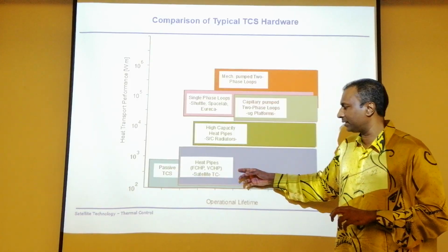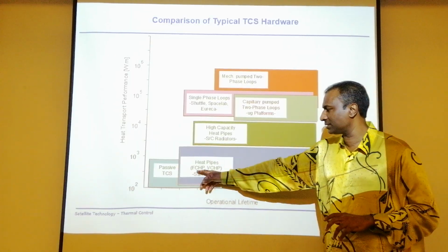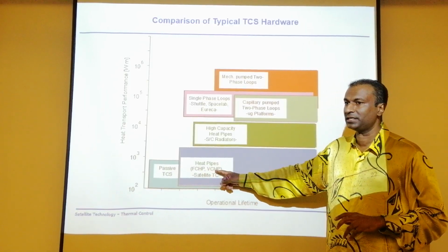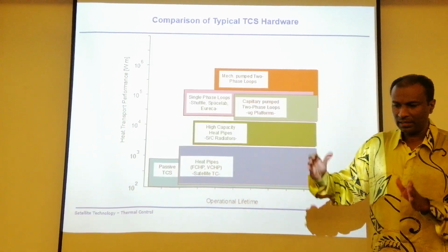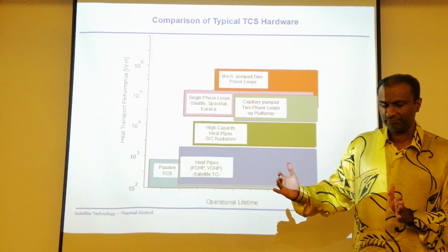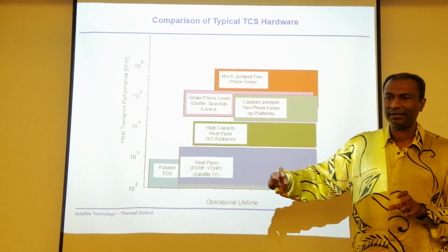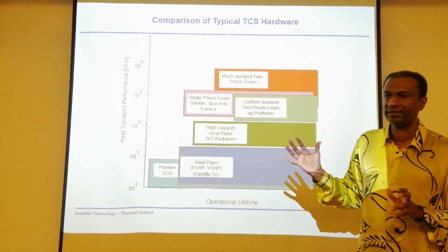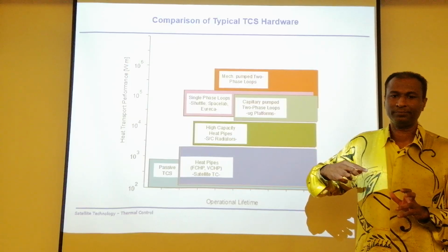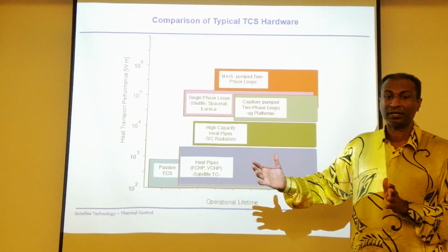Then you have types of heat pipes basically for satellites. This is a fixed conductance heat pipe. This is a variable conductance heat pipe. Fixed means the transportation, let's say you have a particular distance, the conductance of it, that means the capacity of heat rejection, is fixed throughout the system, or you can have multiple kinds of conductance. That means the conductance can be different.